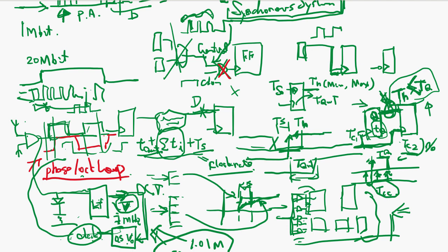Then within this preamble period, you can completely synchronize your clock with this one. Then using this clock, you detect and receive the data. Okay, so this is kind of an asynchronous data transfer design. This is one of the typical methods to use. So this is completely logic hardware design, and when you cannot do this analog portion, then you have to digitize this. Digitizing this gets more complicated because you need to have a stepping delay time circuit.